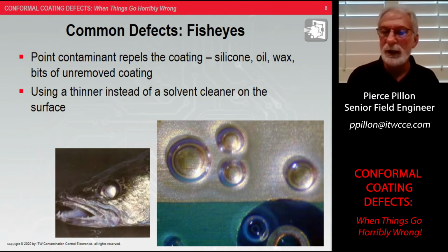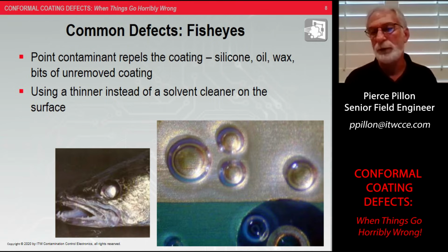If you're cleaning an area, especially a rework area, don't use the same thinner that you're using for your coating if you have a selective spray system or a spray gun, because sometimes that is not the proper solvent to clean those residues. And what that ends up doing is now you just smear that residue around that area. It just doesn't properly dissolve and remove a lot of these contaminants.